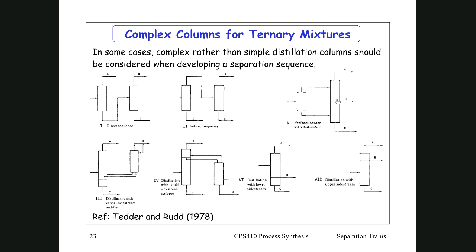I think it does, simply because this part doesn't require a reboiler. So the only reboiler you've got is C. Okay, so, thank you. So C alone would obviously need a smaller reboiler than the reboiler here in the direct sequence, because that would consist of B and C. It's a bigger flow rate, and you probably need a little bit more reboiler energy there. Yep. So it's a really beautiful design. Thank you very much, sir.